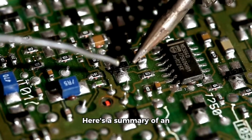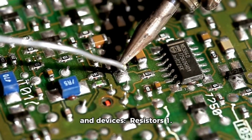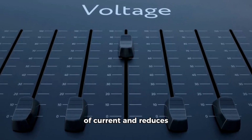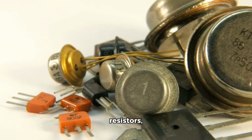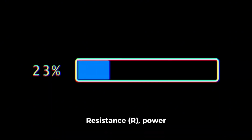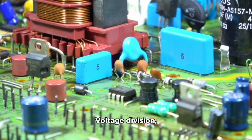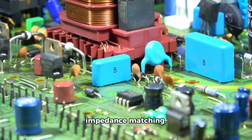Here's a summary of an introduction to electronic components and devices. Resistors. 1. Definition. A component that opposes the flow of current and reduces voltage. 2. Types. Fixed resistors, variable resistors, and thermistors. 3. Characteristics. Resistance (R), power rating (P), and tolerance (%). 4. Applications. Voltage division, current limiting, and impedance matching.